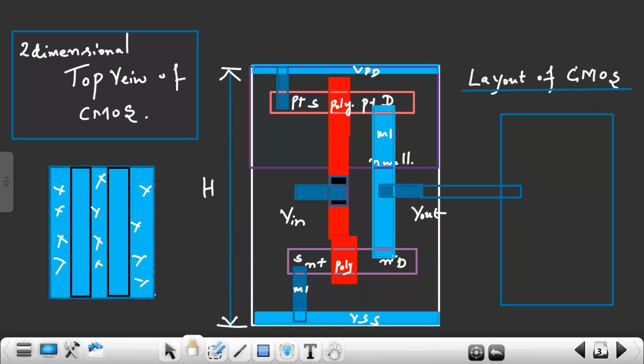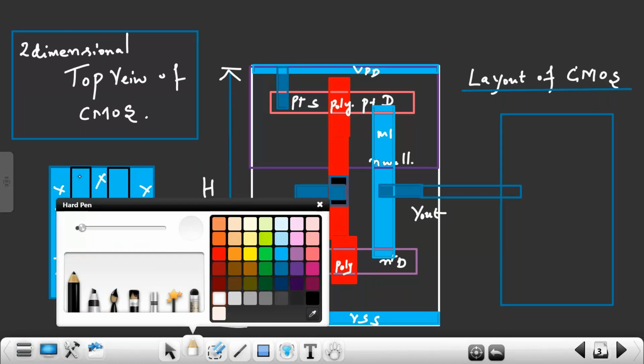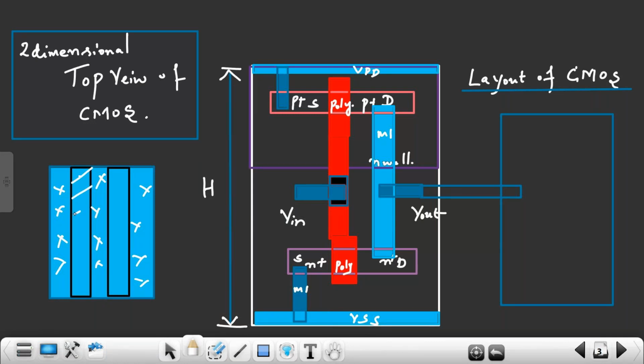So what I will do is, this portion where I have to retain the metal layer, I'll cover by oxide layer. This I'll cover by what? Oxide layer, by using a mask. Other regions I will treat with high concentrated acid. Other layers will etch away, because I'm treating with high acid. These layers will etch away. These layers will not etch away. These layers will be as they are.